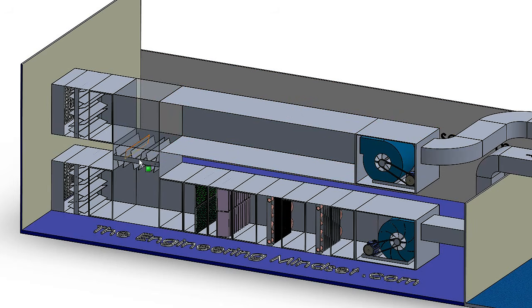So by having these damper arrangements here, you can divert some of that back in, and it will usually depend on outside air conditions for one, and also the level of CO2 in the room or in the return duct here. And if the conditions are right, then it will channel some of that back in, and that means that the heating coil will not need to do as much work, or maybe the cooling coil, maybe the humidifier will not need to work. So you will save money by returning some of that air back into the system.